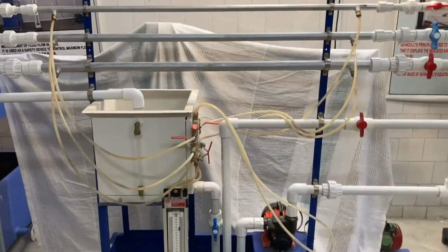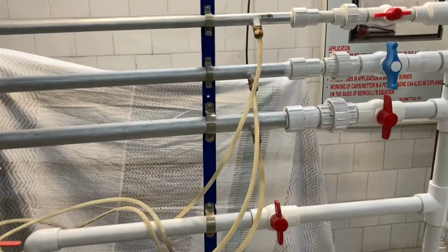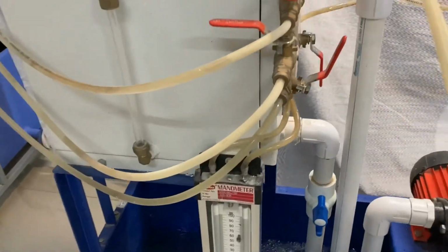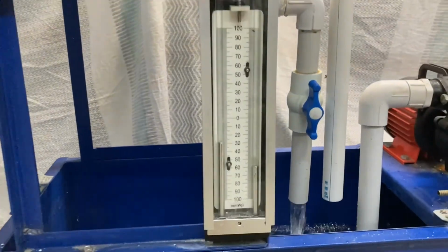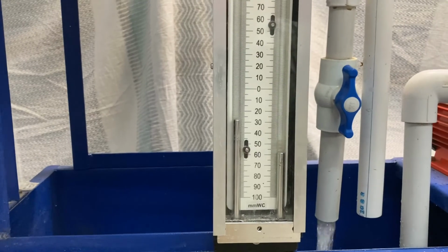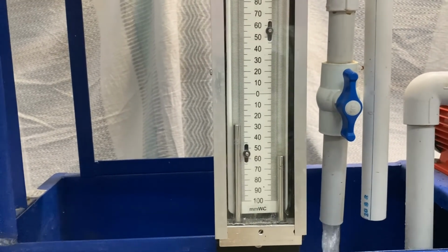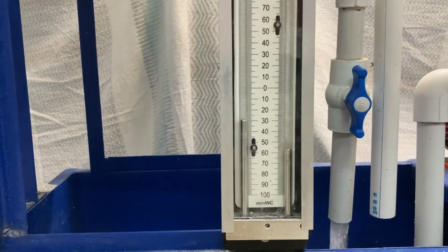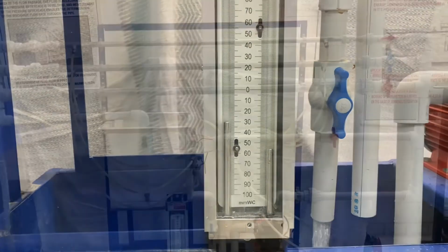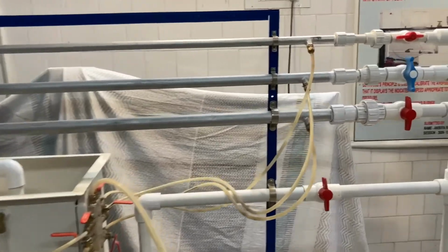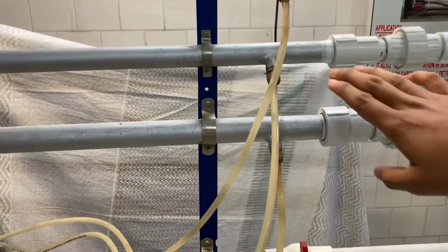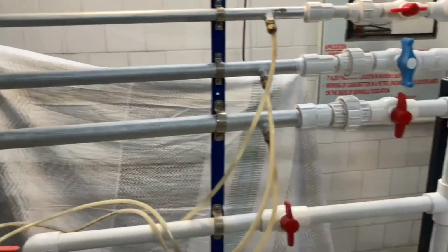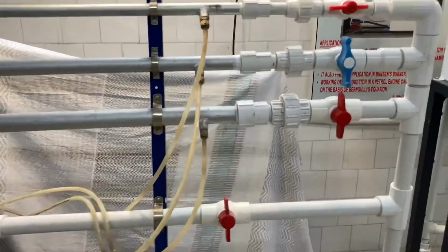Now the valve of the smallest diameter pipe is open, and also these manometric valves are open, so we can see the reading for the smallest diameter pipe, and we can clearly see the reading. The deviation is maximum here. This deviation was very less in the case of the largest diameter pipe. Here initially I had chosen the pipe of largest diameter and then the smaller one, so that we can get maximum deviation in the manometric reading.